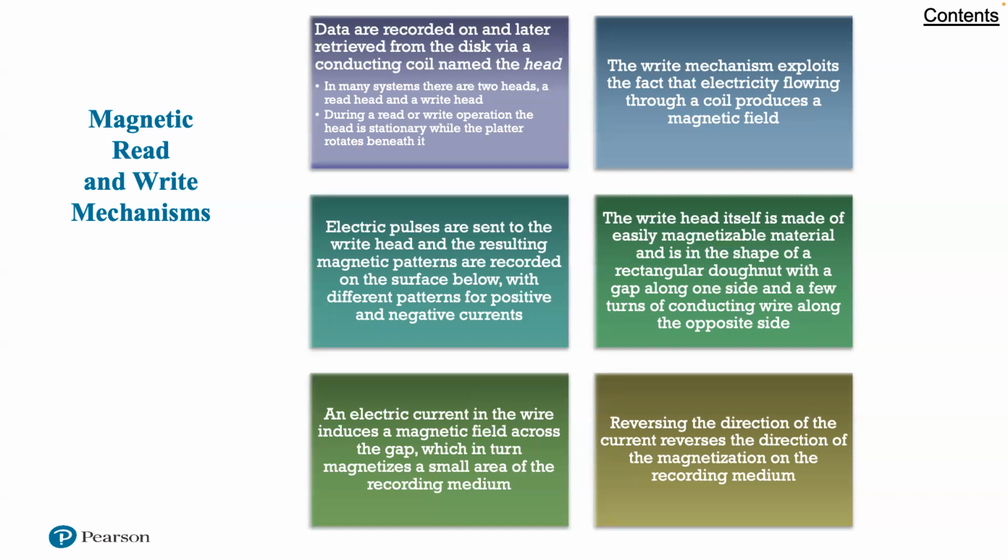Contemporary rigid disk systems use a different read mechanism requiring a separate head, a read head positioned for convenience close to the write head. The read head consists of a partially shielded magnetoresistive (MR) sensor. The MR material has an electrical resistance that depends on the direction of the magnetization of the medium moving under it. By passing a current through the MR sensor, resistance changes are detected as voltage signals. The MR design allows higher frequency operation, which equates to greater storage densities and operating speeds.